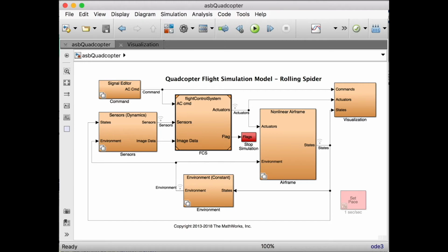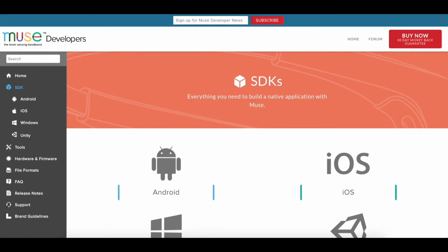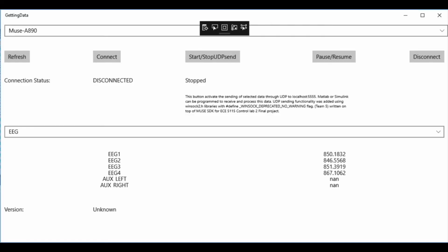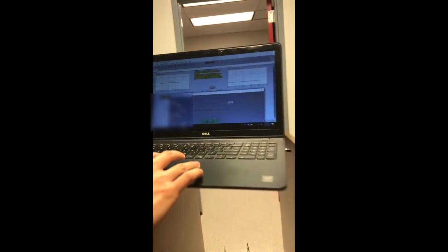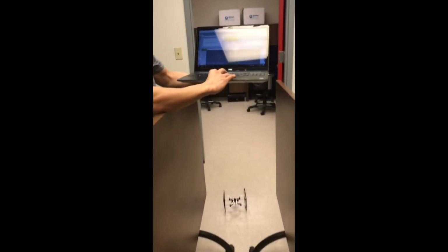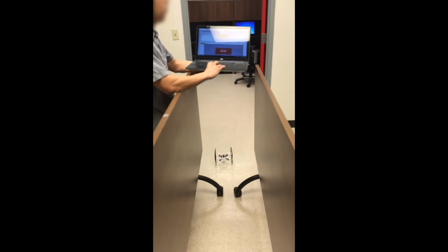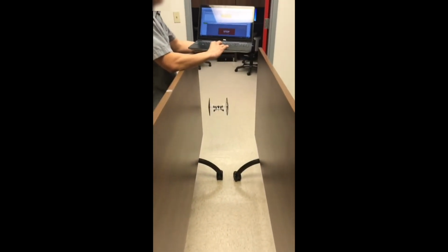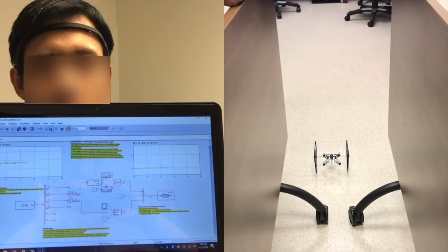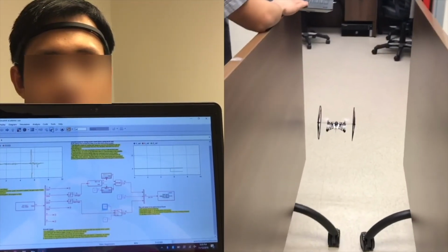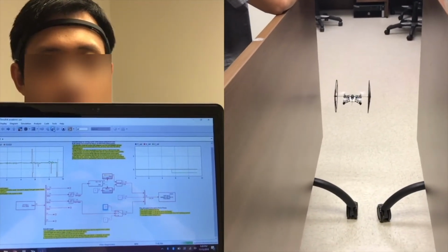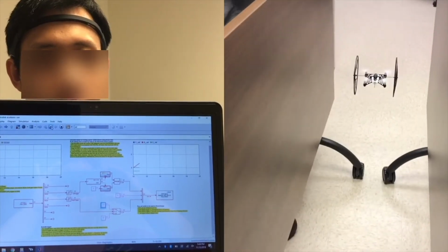The main bulk of our testing and experimenting came from the initial research of the parts and programs. The blinking threshold also required testing. We wanted the user to have to hard blink so the drone would not stop or start accidentally. Overall, this led to a successful run. As you can see, the goal was to get left and right movement using the Muse headset. However, due to the noise in the data, we used blinking.